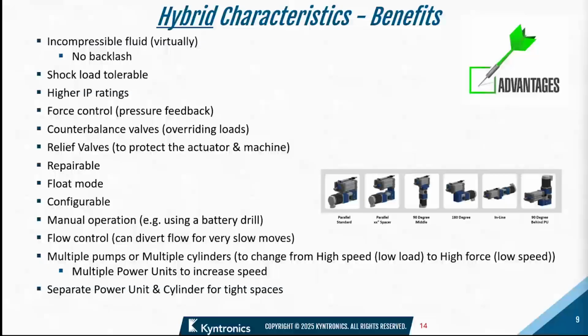Some of the hybrid characteristics of the fluid, some of you are aware of it, some may not be. Let's go through some of these. It's basically an incompressible fluid. Nothing's totally incompressible, but for most applications, the forces involved don't compress the fluid, so you don't have the backlash. Shock loads are tolerable. Shock loads are not an issue with our unit. We need to keep the fluid inside. Therefore, we have high IP ratings. We can go up to IP69.